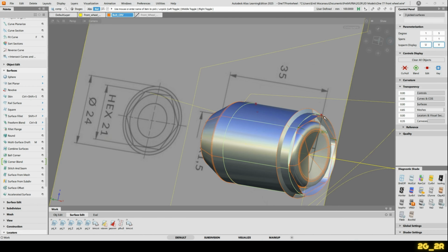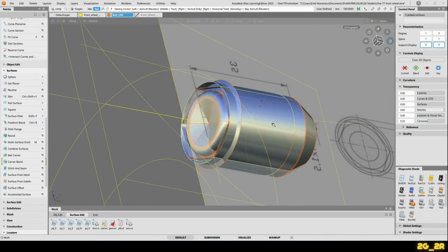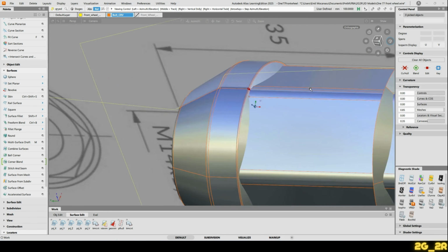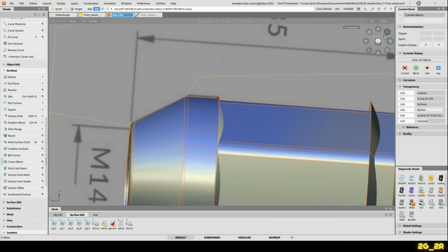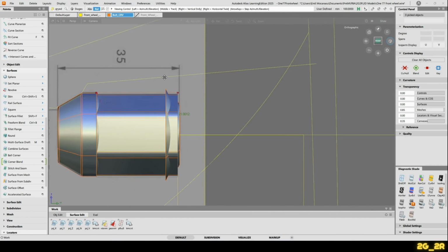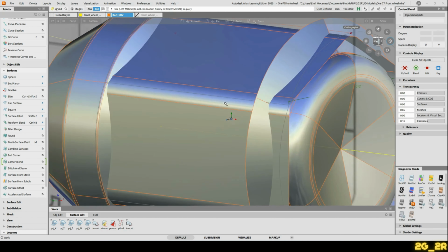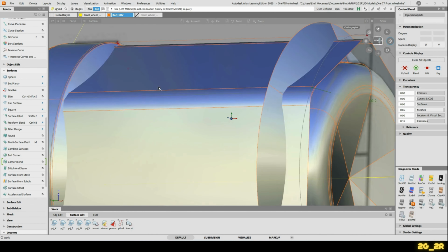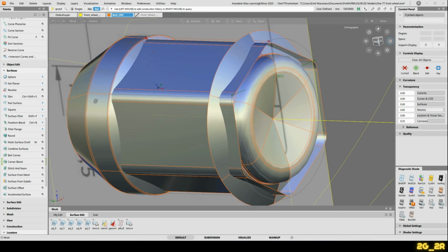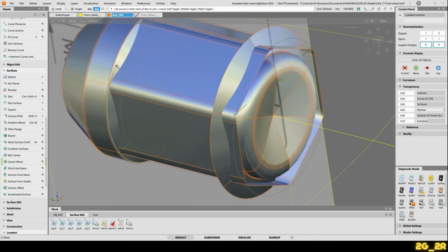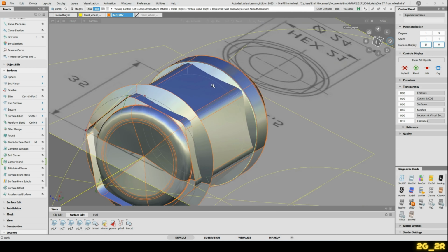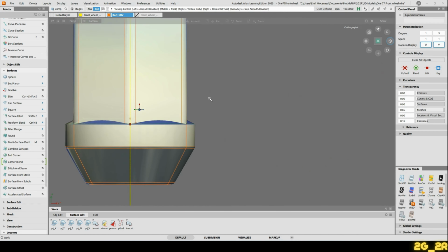This set of surfaces, we can template back. But because we've adjusted that selection, it recalculated the whole rotational object, and we've lost the history on those skins, but it's all good. It's all done now. So what we need to do is pick these surfaces now, and we will be going into another basic tool now. We will intersect them.